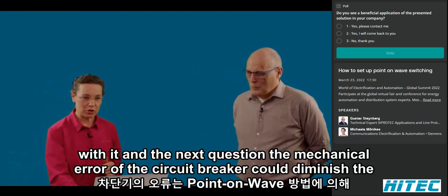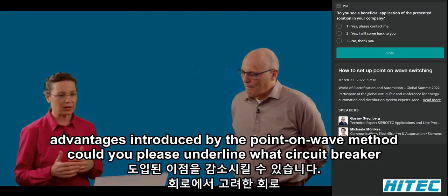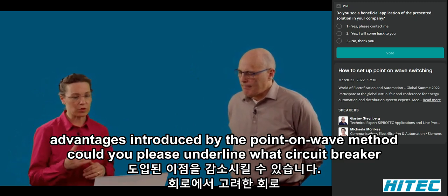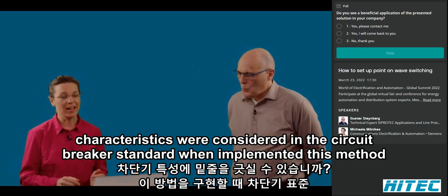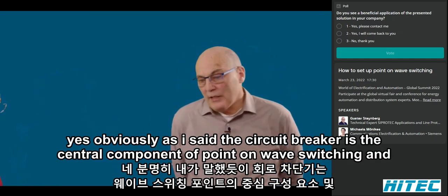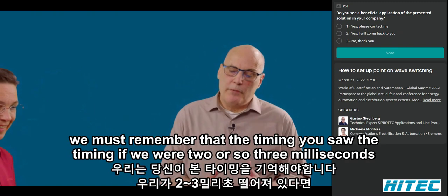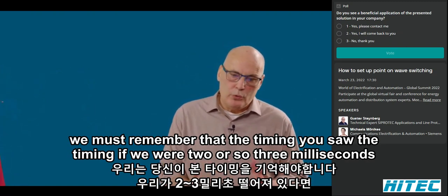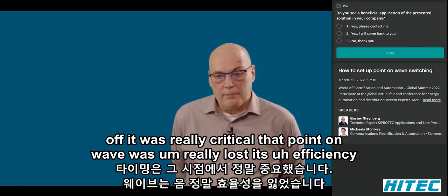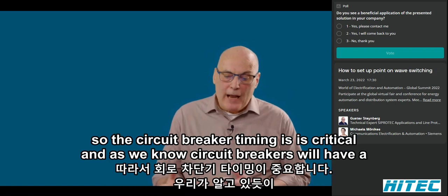And the next question. The mechanical error of the circuit breaker could diminish the advantages introduced by the point-on-wave method. Could you please underline what circuit breaker characteristics were considered in the circuit breaker standard when implementing this method? Yeah, as I said, the circuit breaker is a central component of point-on-wave switching. And we must remember the timing: you saw that if we were 2 or 3 milliseconds off, it was really critical. The point-on-wave really lost its efficiency. So the circuit breaker timing is critical.